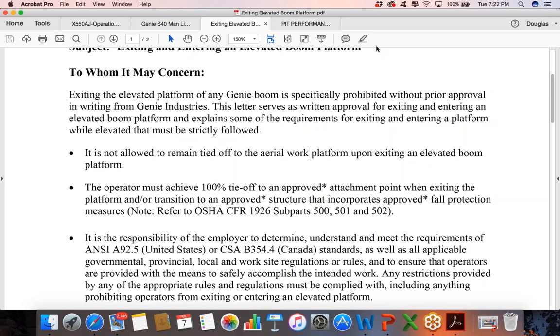We can't wear them when it comes to hot work or steel erection. Why? Because the cuffs can catch any type of sparks or slag, just like laces could in a lace up boot. Okay, and it could start a fire or significantly injure the employee. Also, pockets on shirts have to be covered with a flap, or they have to not have a pocket at all. So we cannot have a pocket without a flap, and we cannot have a pocket with a flap that's tucked in. It's going to have to be tucked out and over so that no fire hazards enter that pocket. Okay, and it'll keep any type of flying debris or sparks or any other loose materials from getting into the shirt.